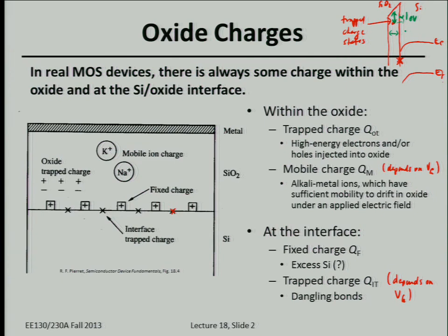So if you plot the current flowing in a transistor from the source to the drain, where you apply a gate voltage and a source drain voltage and measure the current, you see it changing with time, because of this trapping and detrapping of carriers. In reality, yes, that does happen, and it leads to what we call random telegraph noise. Noise is actually a practical problem in designing low voltage circuits today.